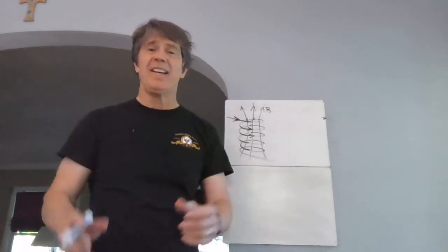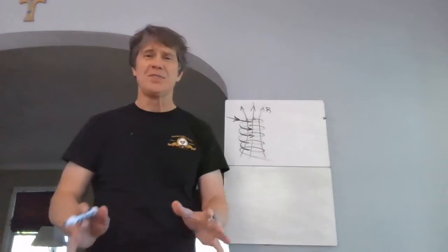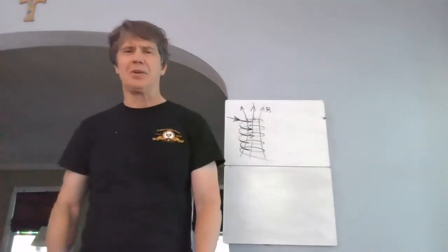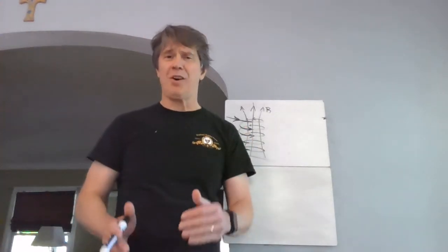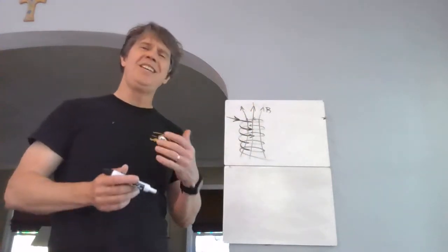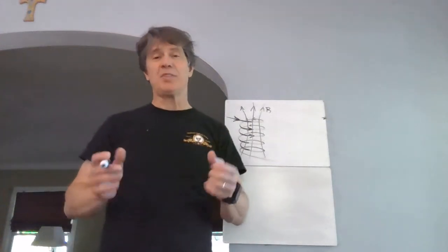It's going to fight. In fact, it's going to fight the change, which sounds like, I might have said that before, like Lenz's law. It's not that you fight a current flowing one way or fight a current going the other way. It's not that you're liberal or conservative. It's just you don't want anything to change. So no matter where you are, you fight the change. So an increasing current is going to yield this. It's called a back EMF because it fights back against the change.